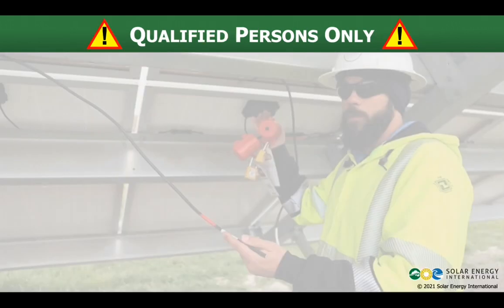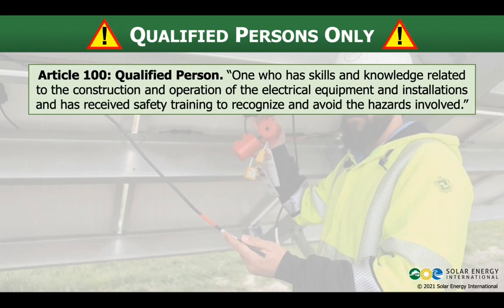Before we go further, let's note the requirement for qualified persons only that's laid out in the National Electrical Code in regards to solar PV systems and installing them in special conditions. So first, let's turn to Article 100. These are definitions, and you can go through there. There's a lot of information in there. There are some definitions that are super critical to PV systems, but they live in the front of the book. They don't live in Article 690 about PV systems because they're referenced in a bunch of other areas in the code book as well. So we want to have them in the front. But one example is the definition of what a PV system is. It's in Article 100, not Article 690.